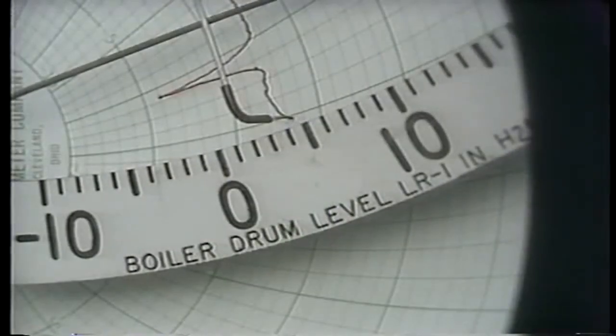In most cases, a leaking boiler tube does not significantly affect a boiler's ability to circulate water or steam. However, a tube leak is an abnormal operating condition and has the potential of damaging the boiler if not carefully monitored. When a tube leak occurs, hot water or steam is released from the tube under very high pressure. If the leaking water or steam comes in contact with other boiler tubes, it can cut through those tubes and cause other leaks. If an operator isn't careful, a small leak can snowball into a major problem.